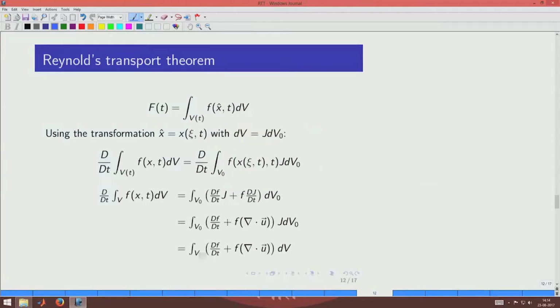The idea is as follows. If you take any quantity that is expressed as a density, then if you integrate it over the control volume, you get the quantity out. Take the example of small f. If small f happens to be rho, then the capital F would be the mass. And in the case of small f being the concentration, the capital F would be the amount of solute for that particular quantity.